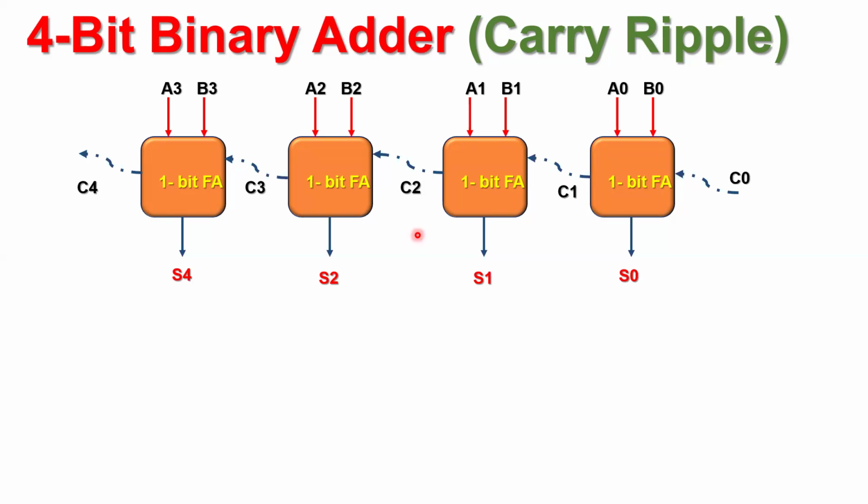In the modern ALUs, arithmetic logic units, where the adders are an integral part of the ALUs, and ALUs are part of microprocessors or DSPs or microcontrollers, the bit width of the adder circuit is 64-bit minimum, 128-bit, 256 bits, and so on. So that is the function and the concept of the full adder.